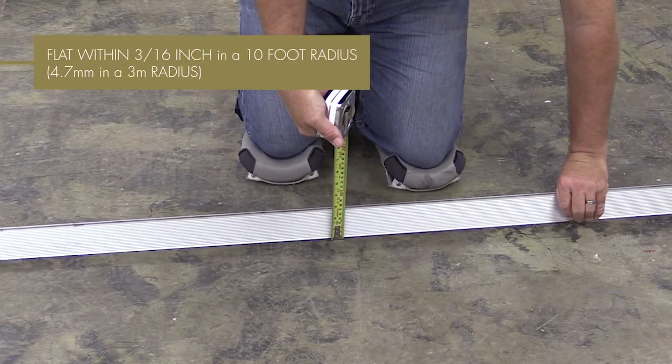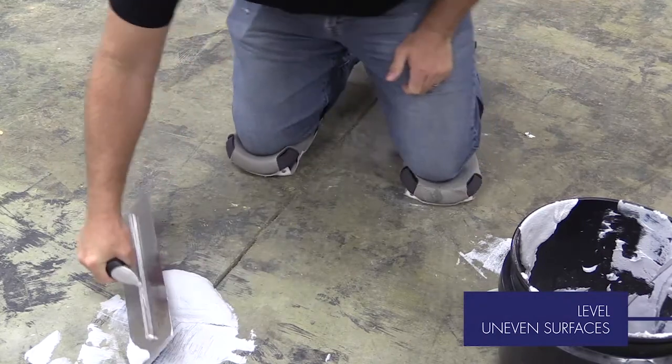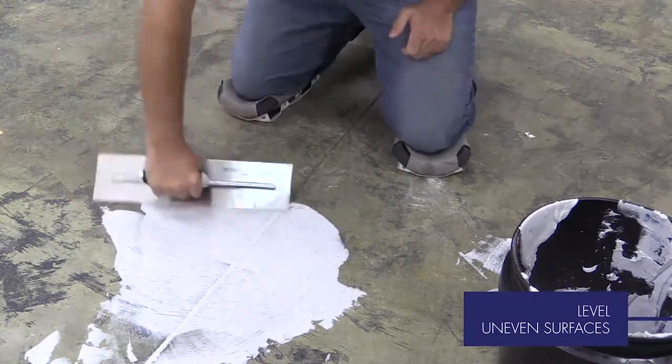Substrates must be sturdy, sound, and flat within 3/16 of an inch within a 10-foot radius, 4.7 millimeters in a 3-meter radius. In addition, the substrate should not slope more than 1 inch per 6 feet in any direction, 2.5 centimeters in a 1.8-meter radius. If necessary, fill large cracks or voids with cementitious leveling and patching compound.